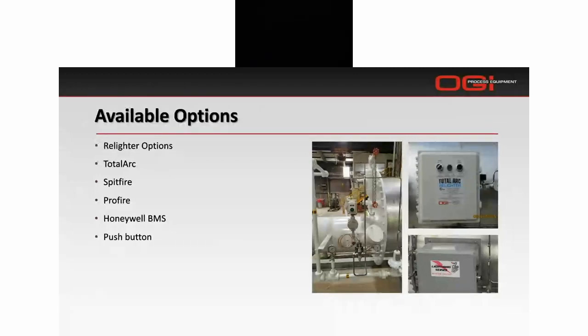We usually go with this setup for compressor stations or for fuel gas heaters where we may be putting on an Allen Bradley PLC and communicating with the gas turbine. So this is more for a high-end application. On a general meter and regulator station water bath heater, you probably wouldn't want to put that on. But I do know some customers have very stringent safety standards that they're trying to develop and advance, and they want all kinds of redundancies, so they may want to use that. And then obviously the very simple end of that would be a push button where you would have to come out and relight it, even if a gust of wind, say, blew out your pilot.